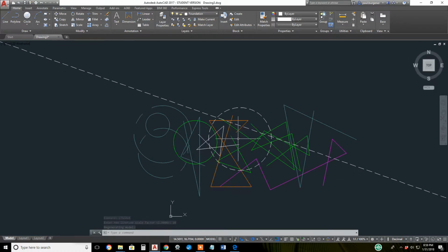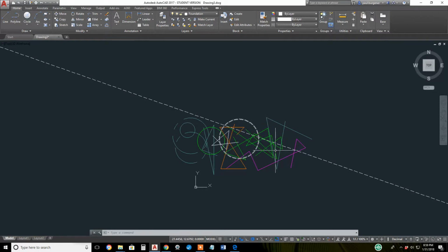So because of that, with the same set of line types, you can draw a 1,000-foot line or a half an inch line. Adjust the LTSCALE setting roughly for the scale that you're going to plot it out on, and you can get along pretty well with the variety of line types that AutoCAD ships with.